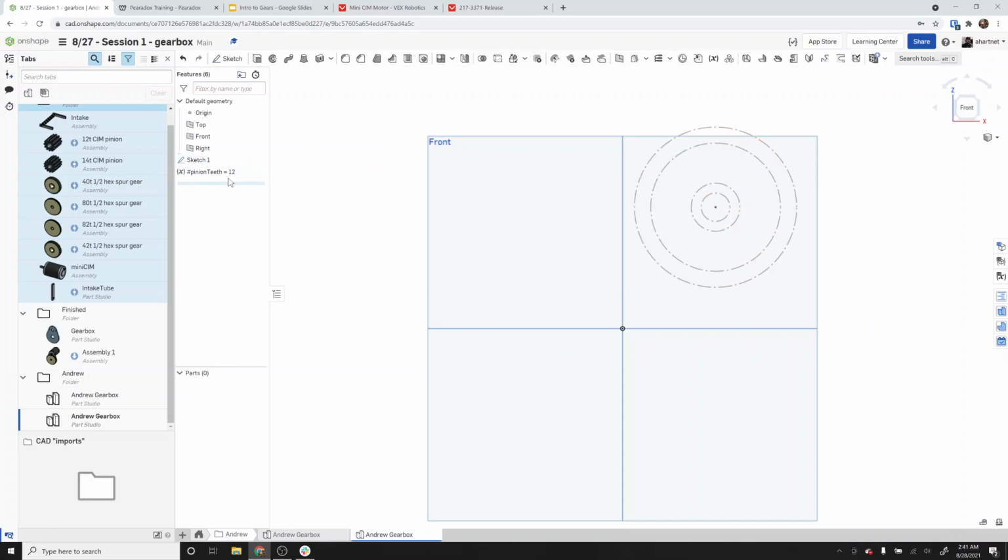That would be okay. I'm going to change it to number because it's not really inches for the number of teeth. And I'm also going to just go ahead and let y'all know that we're going to use 82 teeth for the spur. I'm going to say spur teeth, and I'm going to say 82 for that number. And I'm also going to create a variable called dp for diametral pitch, and that's going to be 20 as a number. Again, you can leave all of them as length. That would be okay. I'm going to change them all to number just because they don't really have a unit associated with them in this context.